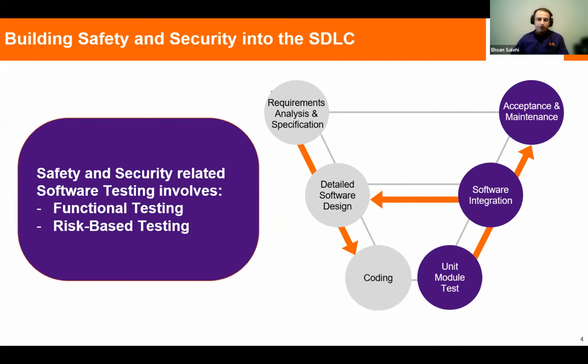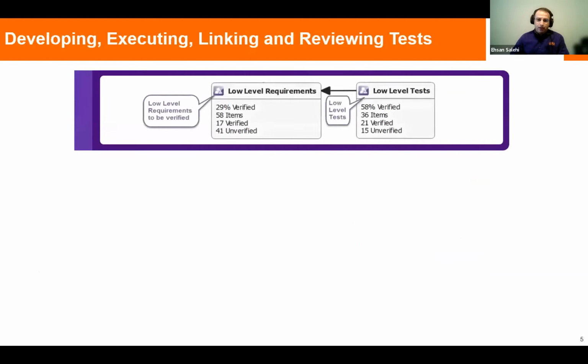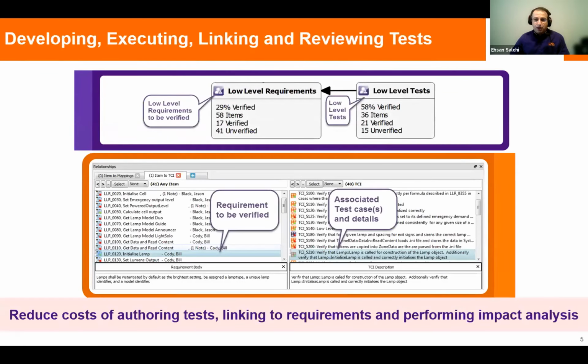So you can see the V model that is used for safety testing. Requirements can be written in a number of different programs, for example DOORS, Polarion, Jama, even Word and Excel. These requirements can then be automatically parsed and brought into tools such as the LDRA tool suite, as you can see on the screen. This particular tool then allows us to see the up and downstream traceability between the system's high-level and low-level requirements. And then the user can see the mapping between the requirements and the source code.